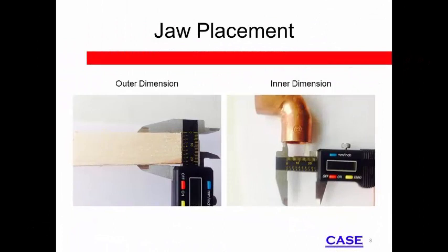The material being measured should be gently touching the material between the jaws. The jaws should not be compressing the material. Compressing the material can damage the jaws and decrease the accuracy of the measurement.